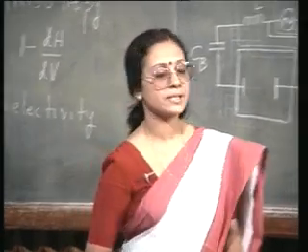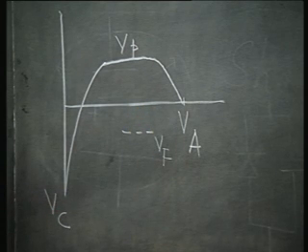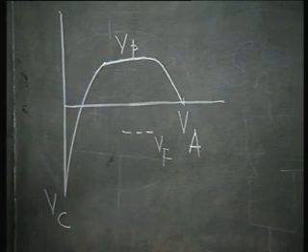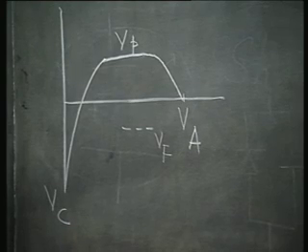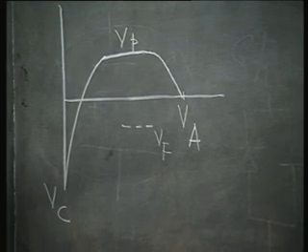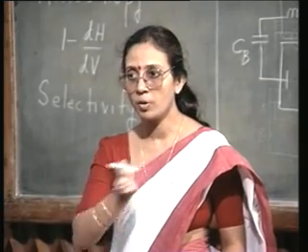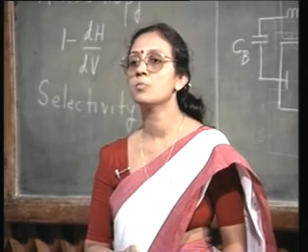Let us say if your substrates are placed on the anode surface, it is going to experience a small ion bombardment energy, because the difference in energy between Vp and Va is not very much, it is a few volts, maximum 10 or 20 volts. So, the plasma glow is at a positive potential, the anode is at 0 potential, the bombardment will be towards the anode, yes, but with a comparatively smaller energy.